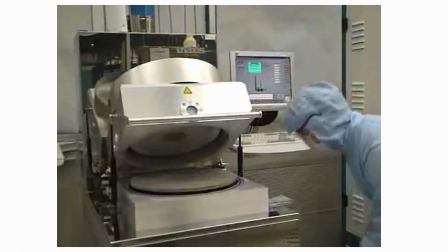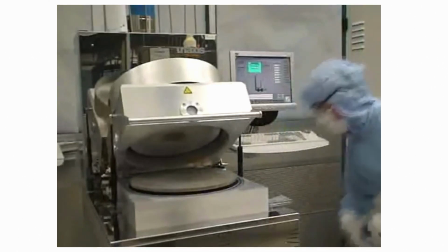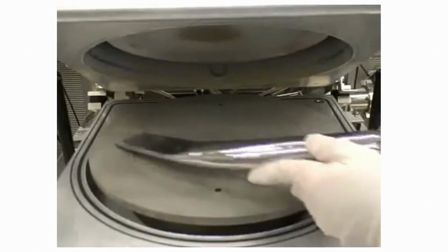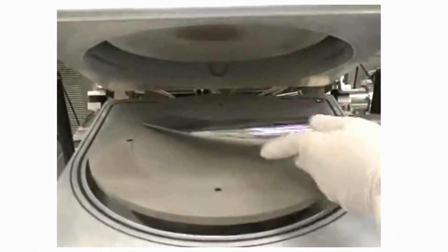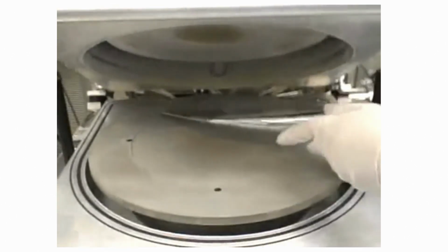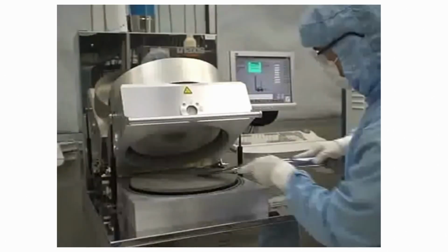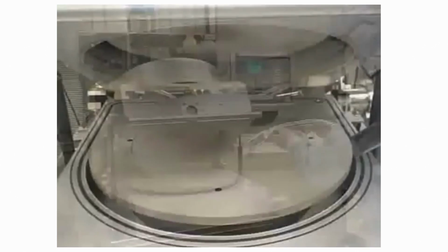Once the chamber is vented, you should begin cleaning the chamber. To do so, you must first locate the vacuum, which should be located next to the system. There should be a flattened metal attachment connected to the nozzle, which was specifically designed for vacuuming the system. Vacuum across the platen as well as under the platen.